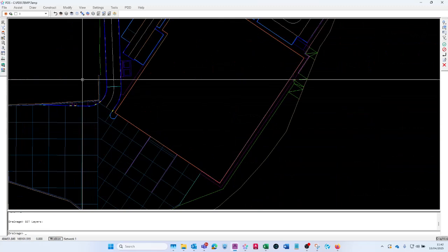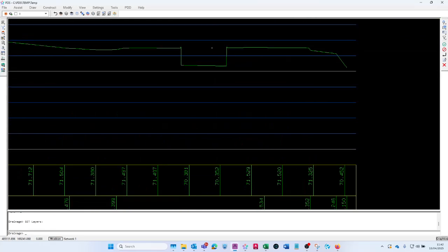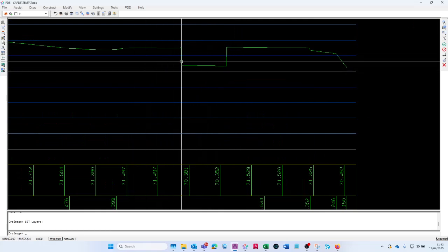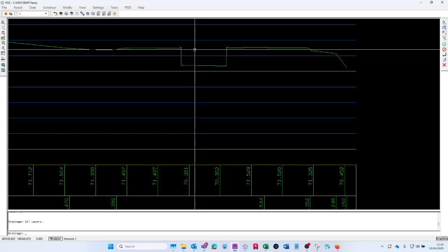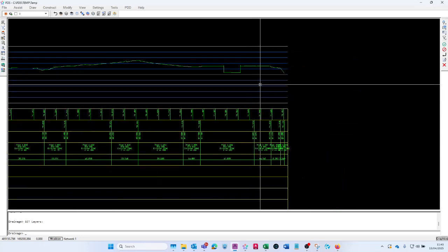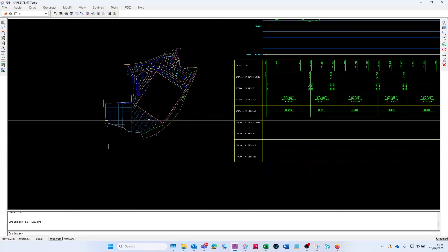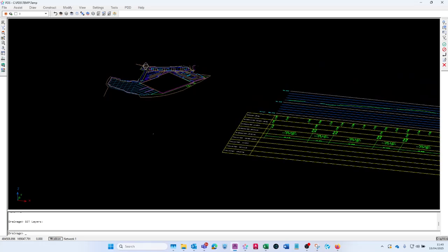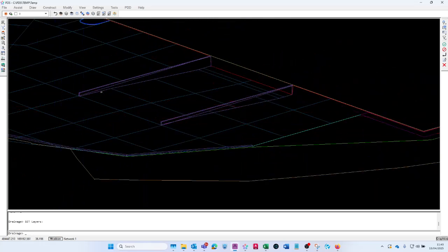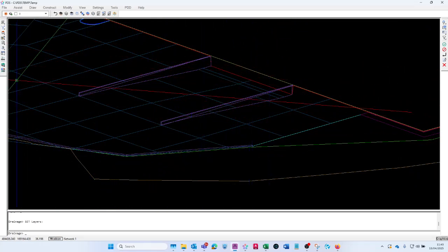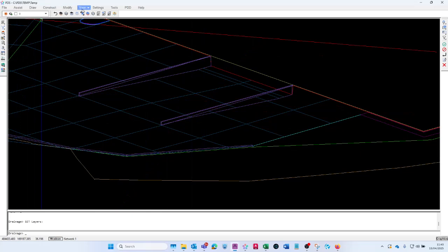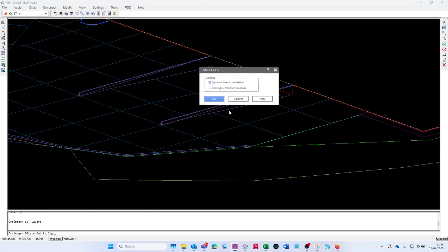And let's fix this lower area here. Drainage comes through this point because this is a dock leveler to go into the building. So the lorry would go down this ramp and the bed of the trailer would be equal to the floor level of the building. So that's what that is. So if we spin this really quickly, there you can see it ramping down to get to the building, and that's the vertical face. So let's modify, delete.